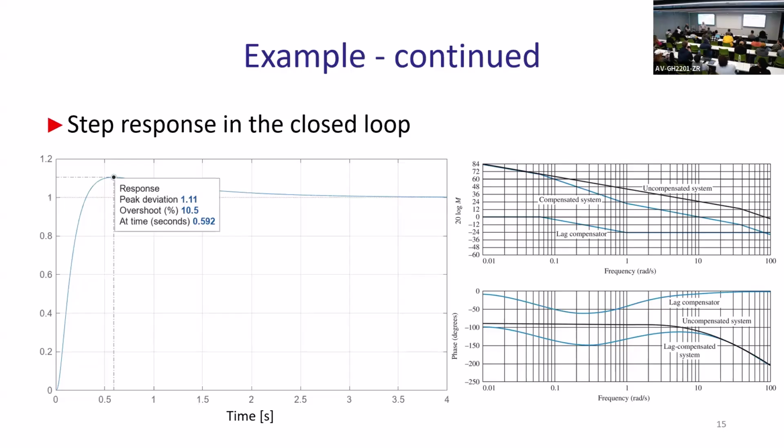So you need to play with numbers until you get 9.5% instead of 10.5%. And other values are close enough. For example, the peak value is 0.59, which is all pretty fast. And steady state error will be also pretty good. So all of the other values are fine, but overshoot is not perfect.